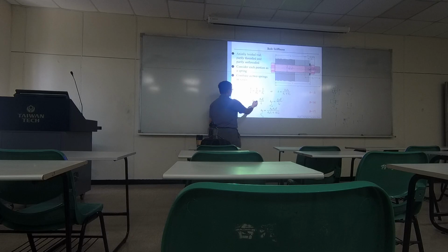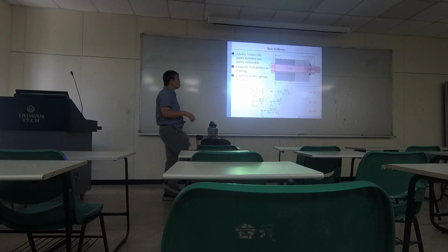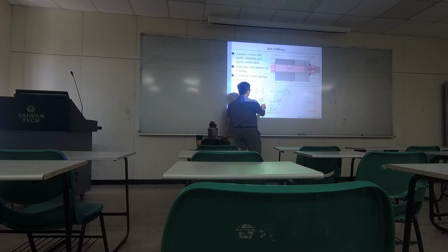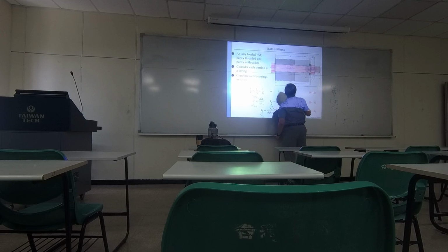So over here, this is the stress area. And that can be provided from the catalogue. It tells you, okay, if you're using this kind of thread, then the stress area should be a certain value. And here is the length of the thread, and here is the length of the rod, okay?